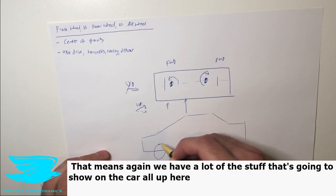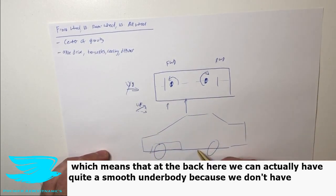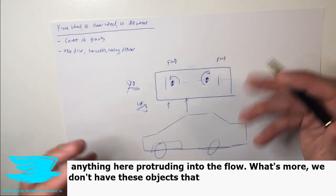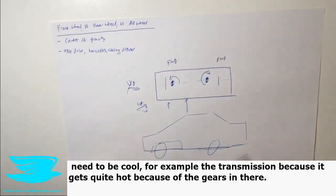So that means, again, we have a lot of the stuff that's controlling the car all up here, which means that at the back here, we can actually have quite a smooth underbody because we don't have anything protruding out into the flow. What's more, we don't have these objects that need to be cooled, for example, the transmission, because it gets quite hot, the gears in there.